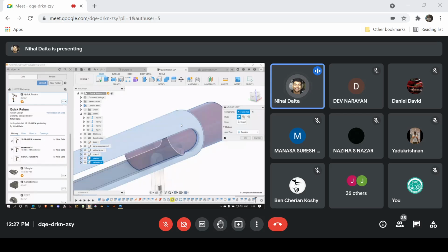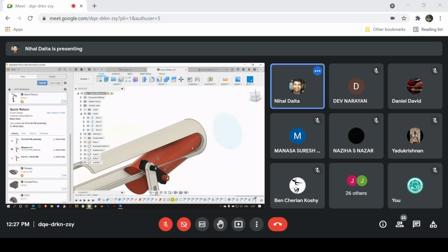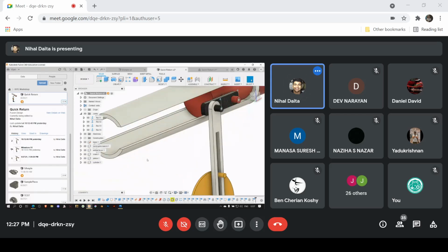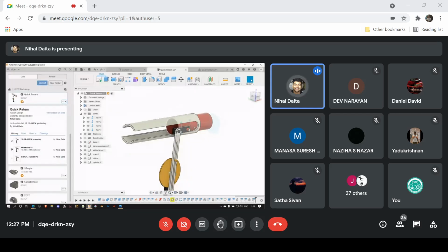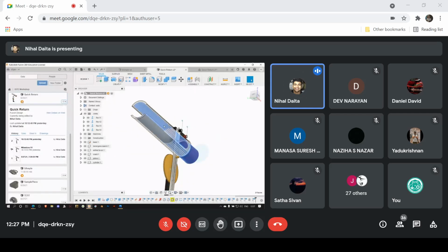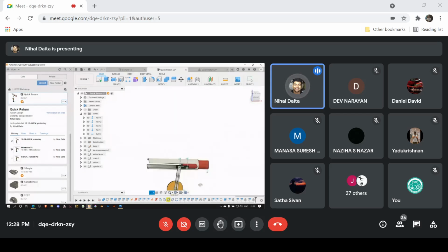Now, if I were to click on both of these and click revolute, no, slider, yes, snap, yes. I mean, it should have worked. Yes, it's not working now. And why is that? Yeah. I guess I have to try cylindrical then. And it's fine. These kinds of problems do happen. Oh, yeah. I just give it cylindrical, it's fine, because the other constraints should hold it in place.